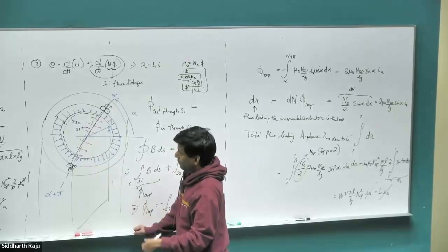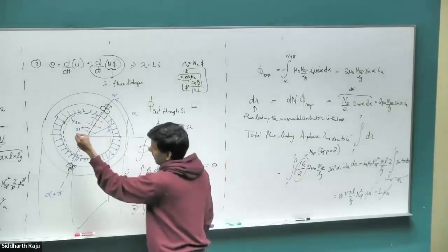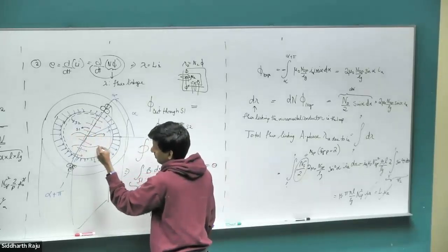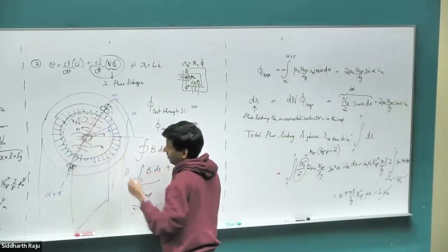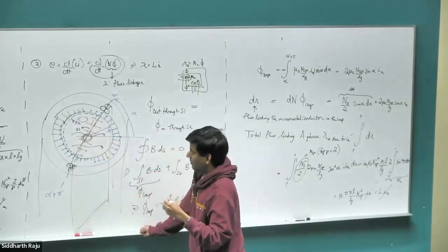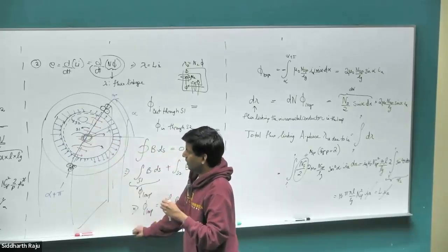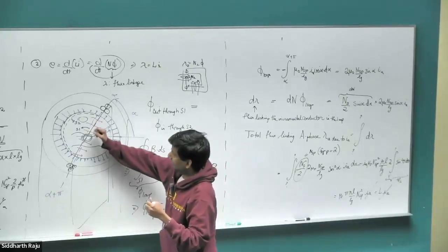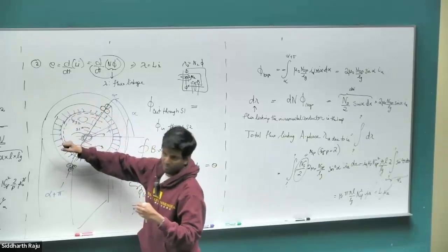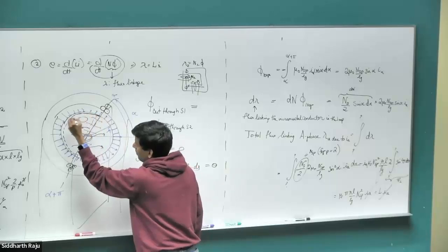So it's quite a complicated picture to figure out what the B field in the rotor is going to be, because it's going to have different structures based on whether you have slots on the rotor, whether you have a rotor shaft, and the different things would contribute to how the B field looks. So we cannot know by analytical expression what the B field in the rotor would look like. But one thing we do know, the answer that Jonah gave, is the B field in the air gap is well known. So once we know the B field in the air gap,